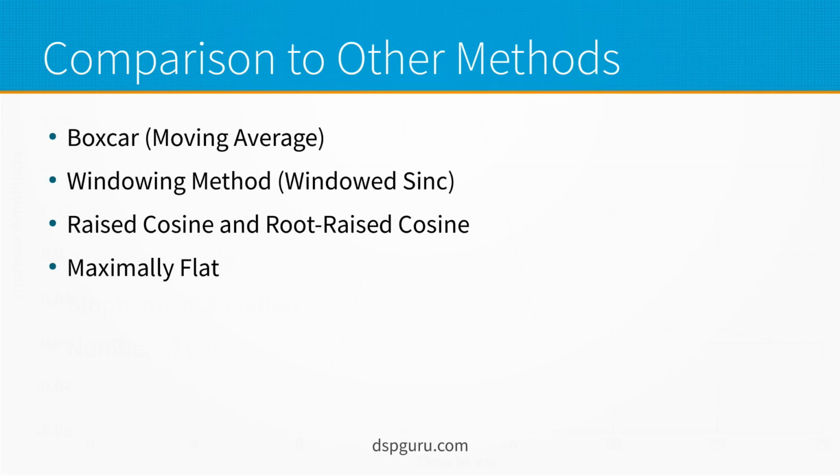That's usually called a boxcar filter. And the key point there is the only parameter we have to work with really is the number of taps. So the larger the number of taps, the longer the average will be. It acts as a low-pass filter, essentially, and you have less noise in your signal as a result of the longer you average.